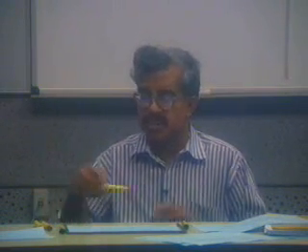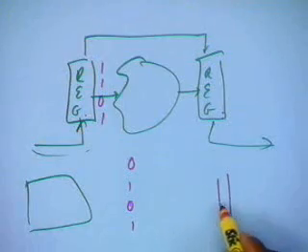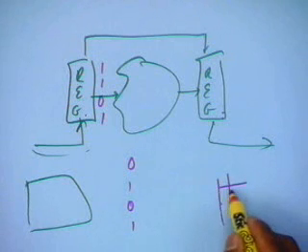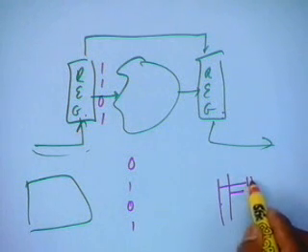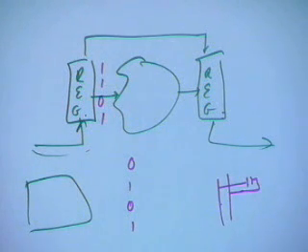But what happens is, dynamic faults actually show up many times because there are two lines which are running very close and they are changing at a very high speed. So, there is a coupling that gets generated between them. Two lines which are so close, actually there is a capacitance type of an effect between them. So this generates a coupling. Such couplings also result in faults, and especially in very high speed circuits which are very highly densely packed.